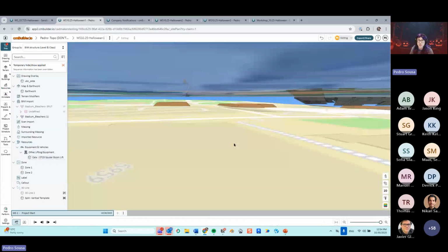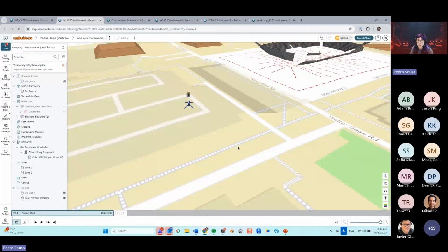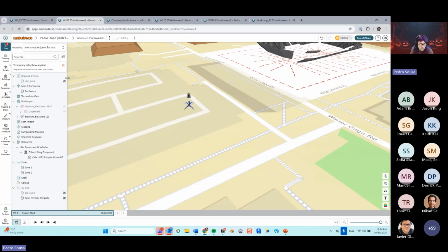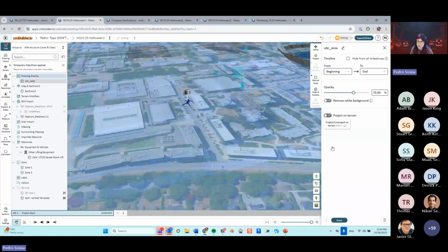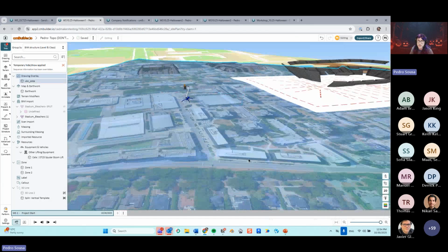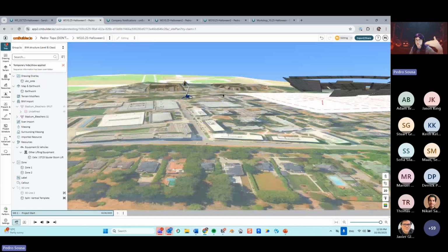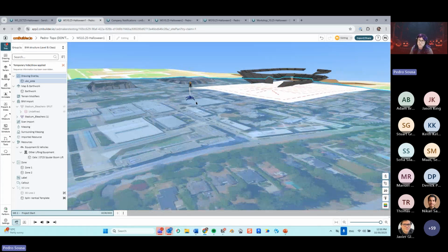And this image is floating, right? So if I hide this image, then you get a floating object. So you need to do one of these two things. Either you make sure you project this on the terrain, because then that image will be flush with the terrain, and every time you place something, it will be placed on the terrain. Or when you're placing your objects, hide the image so you can place them on the terrain.